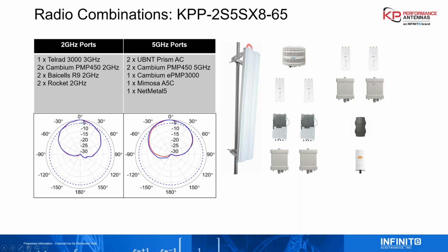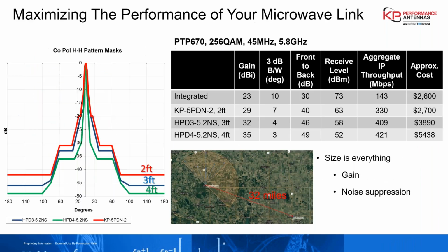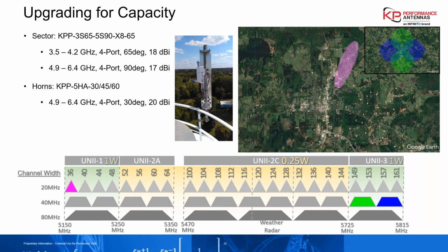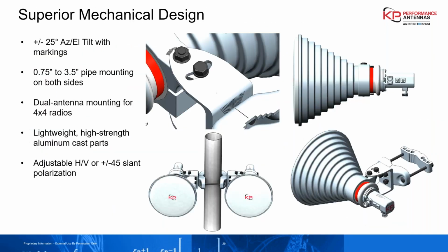Thank you. Another question that came through is, are the nuts and bolts stainless steel on the horn antennas? They are not, and we've heard about this complaint before where they're seizing. So these are going to be galvanized steel, or Dacromet coated, which is a different process than galvanization, but it provides the same amount of protection. A lot of our bolts are either Dacromet or galvanized coating, and we see very similar weatherproofing characteristics between the two. And they don't have the galling issue that stainless steel can have.